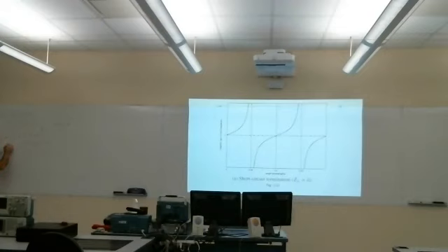So this would actually be back at this point. It's just a general point. L back from the load would be where z is equal to minus L. And our transmission line has a characteristic impedance, Z0, which again for a lossless line is entirely real.